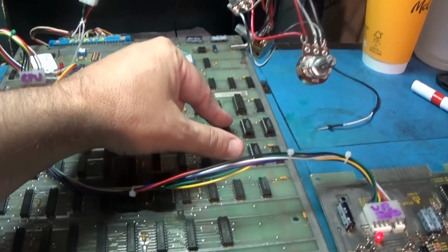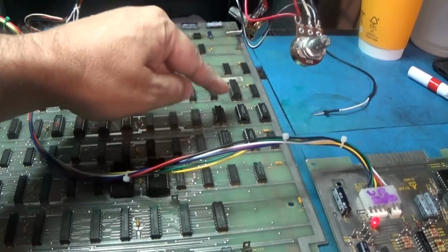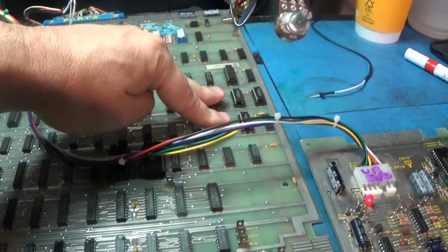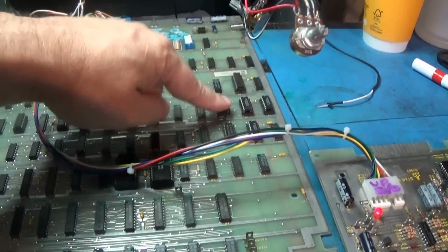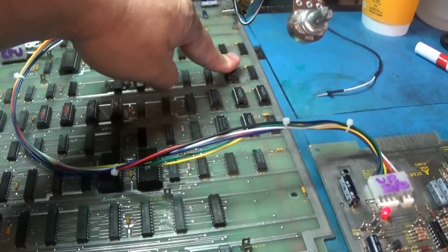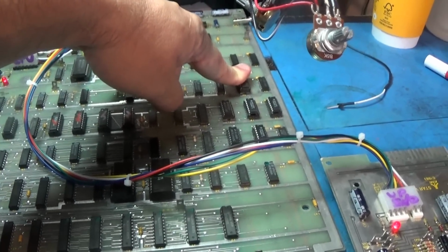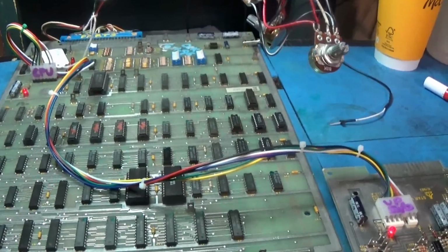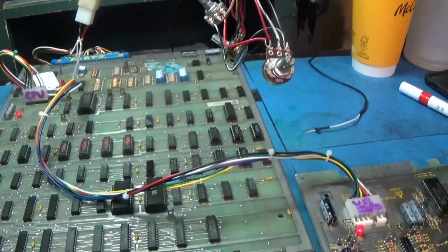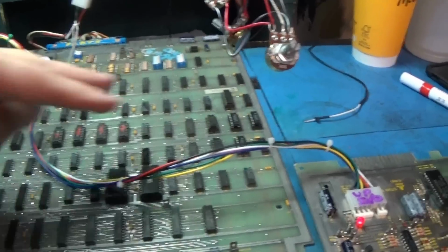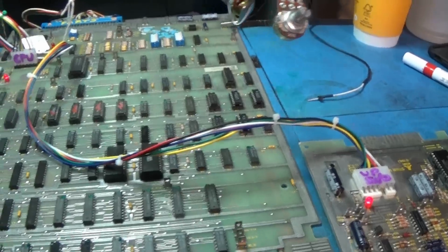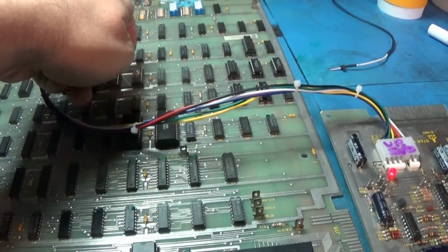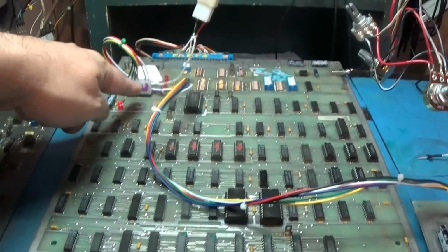I had lifted these 384 multipliers out because I didn't want to test them. I just wanted to replace them and see if that was my problem, and it turned out it wasn't. So I put the originals back in the board, and the subtractor too. Instead of analyzing those, I just lifted them up, socketed them and put new ones in to see if that was my problem, and it wasn't. I did that early on, so I put the original chips back in the board. These sockets were replaced. This socket, I replaced the header because it was really bad.